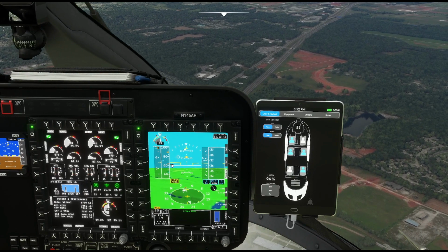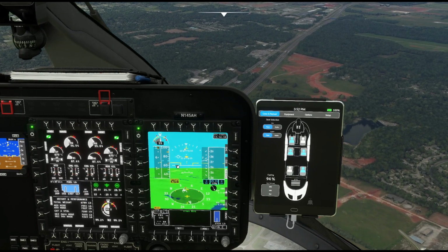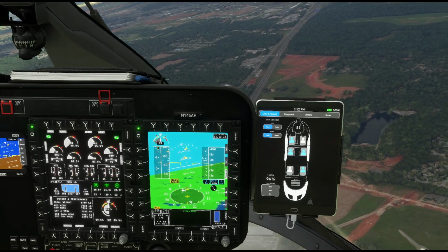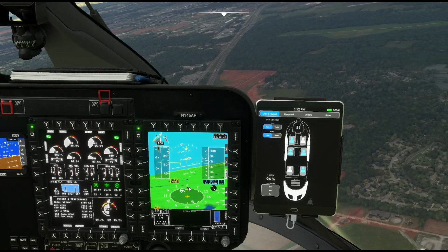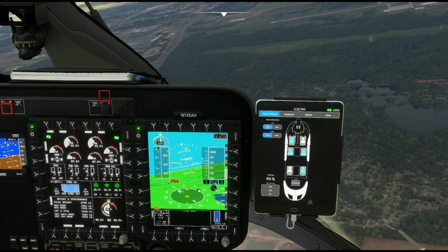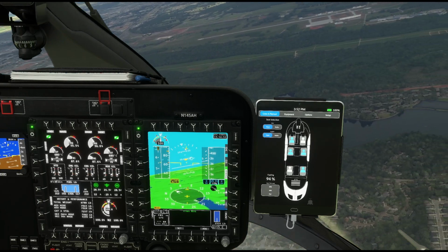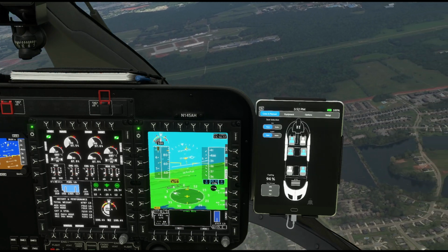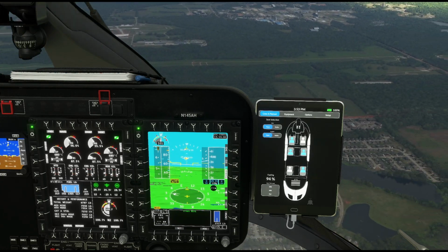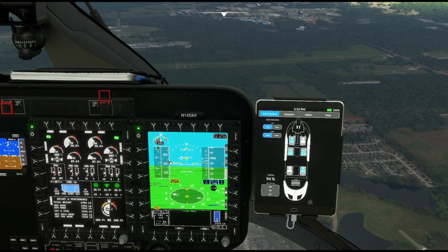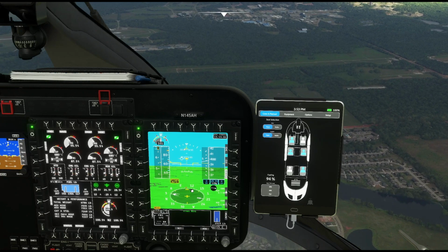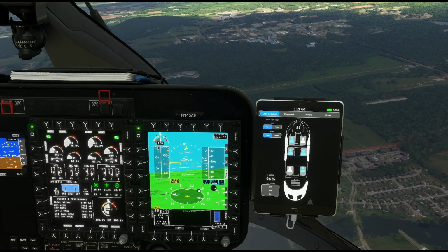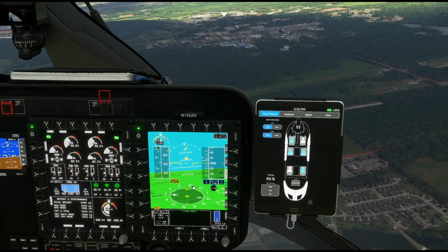All right, so down here, actually, let's go right here. This is our current ground speed, which is less than our actual airspeed because I'm fighting a headwind. Now, if I turn this way, we'll notice my current ground track is going to start deviating off to the side because I will be flying through a crosswind. So we fly that to a crosswind. And now my airspeed pretty well matches my ground speed. Although my ground track seems to be deviating the wrong way. This should be over here somewhere.